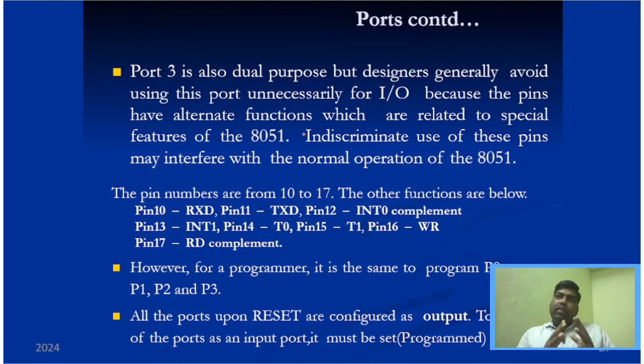As I said, even though there are 32 pins for input output ports, designers mostly will not prefer port 3 for IO, that is, for input output, right? That's because port 3 has some special functions. It can be configured for special functions. You can see pin 10 is used for RXD and pin 11 is used for TXD. All this I'll explain once we see the architecture diagram. Each and every pin will have its own function.